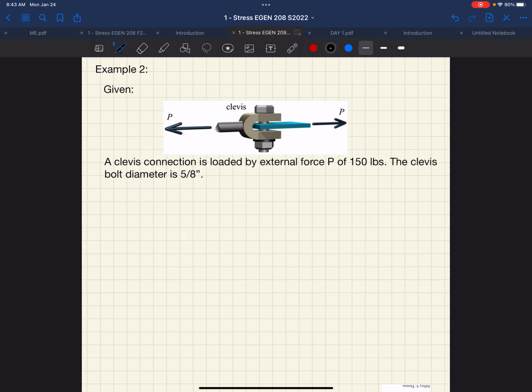If you go to the engineering building, the new one, Norm Asbjornsen, okay? If you walked up on the third floor and you look up, there's a little clerestory. There's a section of the building that's another story higher than the third story, okay? In there, there's a bunch of diagonal braces, big metal rods that are going back and forth, crisscross, across that opening, okay? At the ends of all of those metal rods is what we would call a clevis, okay? It's essentially a connection component that goes into a yoke, right? Big Y section, and allows you to bolt through that yoke into a steel plate.